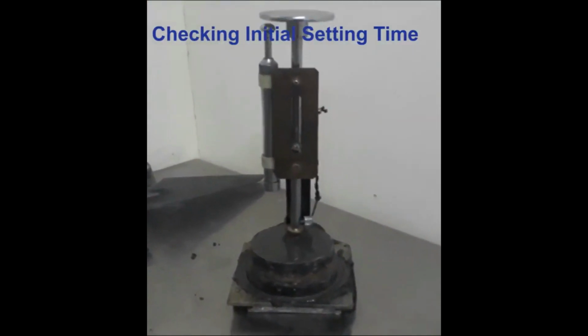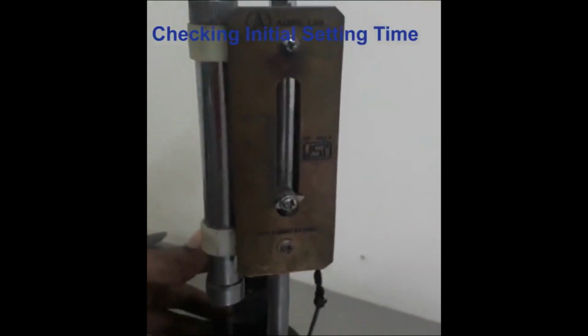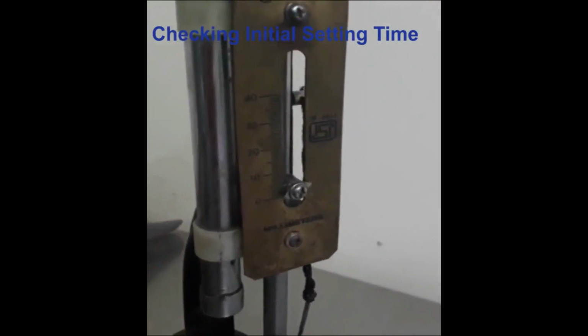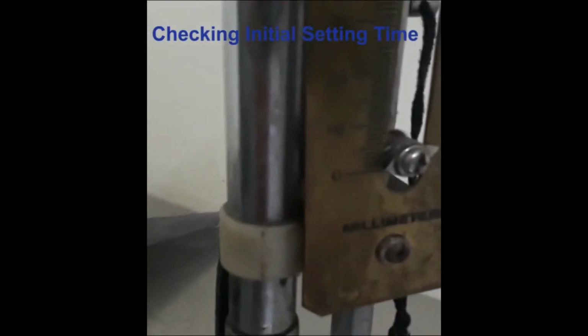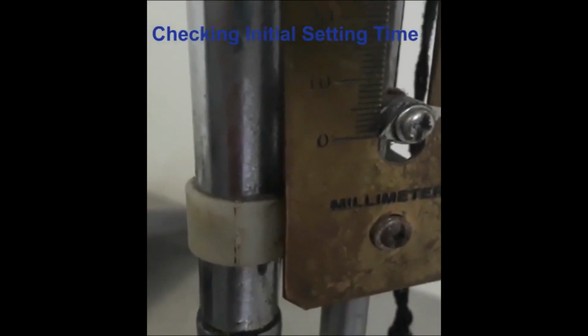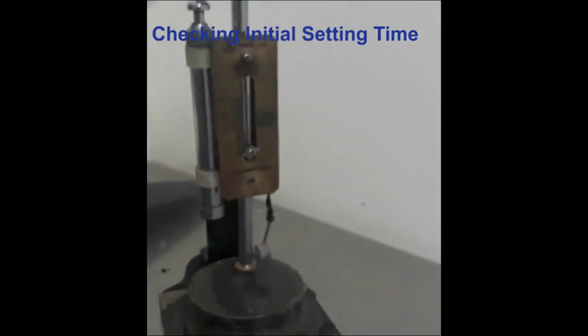Now we will drop the Vicat apparatus needle by releasing the plunger, and we need to note the reading till the penetration of the needle reaches 33 to 35 mm.